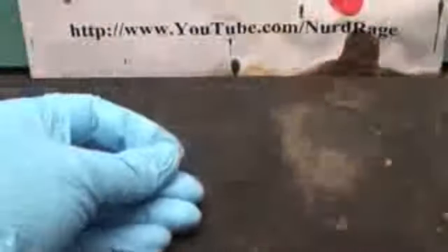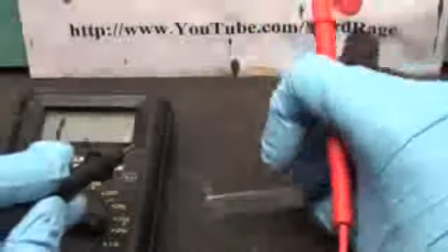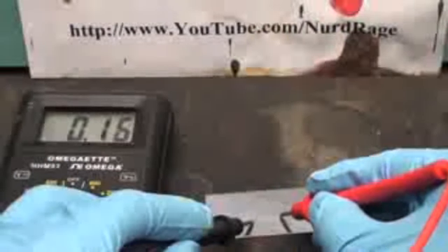Now we get a piece of indium tin oxide glass. This glass is conductive on one side, so to find out which side that is, we get our meter and test resistance. Okay, this side is not conductive. Let me turn it over. Okay, this side is, so this is the side we'll use. Now thoroughly clean the slide with acetone or any other cleaning solution until it's spotless.